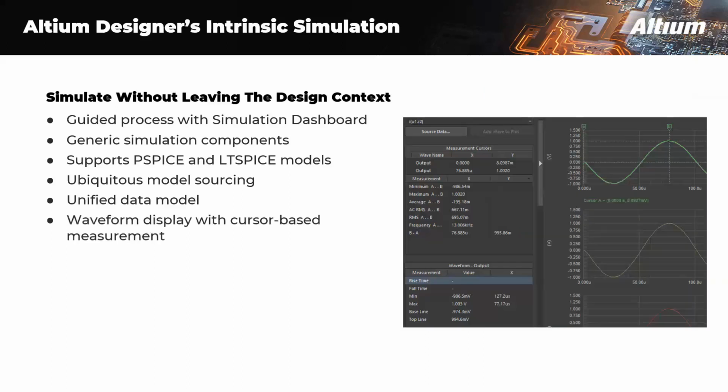The waveform display is treated as a separate tab in the same unified project, just like the schematic, PCB, or ActiveBOM editors. You can tile view, probe across schematics, and perform cursor-based measurements of wave results as shown here.